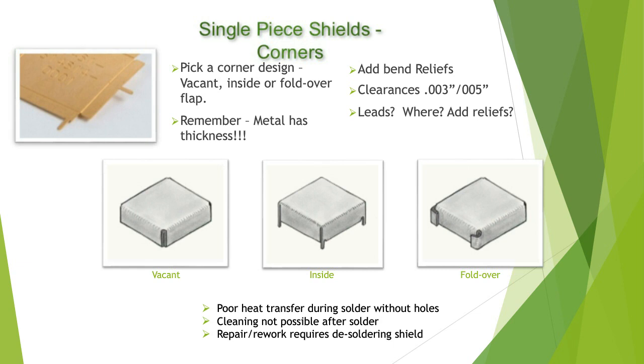You've got to get circuit traces underneath those boards somehow, and I'm sure you don't want this board to short out circuits. Even if they're covered by photoresist now, they may not be long-term. Again, single-piece shields do require desoldering for rework.